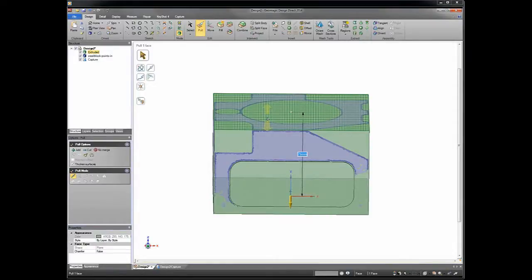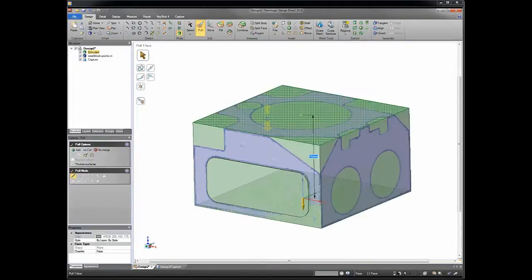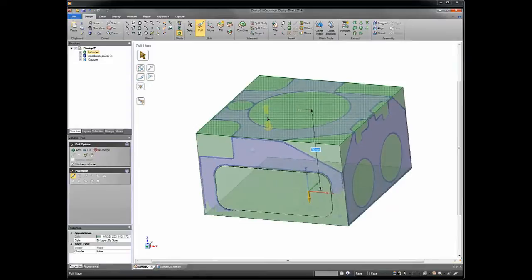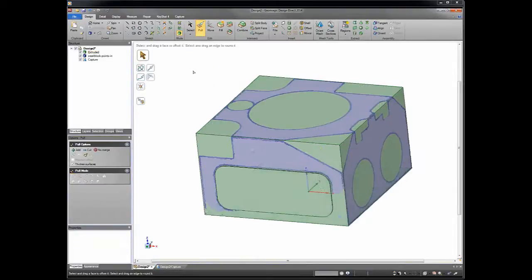You can move these up to a point that you want, or you can key in values. You get the choice either way. It's one of the misnomers with direct modeling that people think it's therefore not parametric. It is very much parametric. It's just not a feature tree. There's not a history tree. If you look on the left, when we get created, we have a single solid. There's not an attached sketch with that.